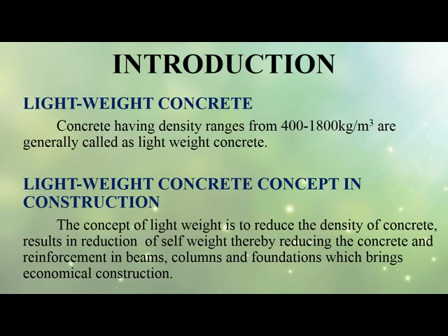Concrete having density ranging from 400 to 1800 kg per cubic meter is generally called lightweight concrete. The concept of lightweight concrete is to reduce the density of concrete, which results in reduction of self-weight, thereby reducing the concrete and reinforcement in beams, columns and foundations, which brings in economical construction.